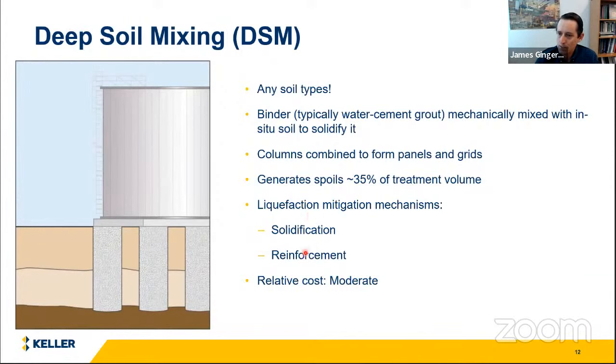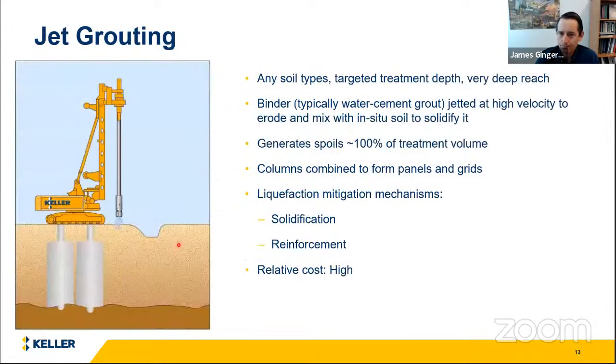The liquefaction mitigation schemes in this case are solidification, so anything that you actually treat directly is solidified, and then reinforcement. You're shear reinforcing the ground, and I'll talk about that in a minute. Keep in mind that the soil between here hasn't been compacted or densified. It's still in its original in situ condition, but that's okay because we deal with it. We mitigate that by the reinforcing effect.